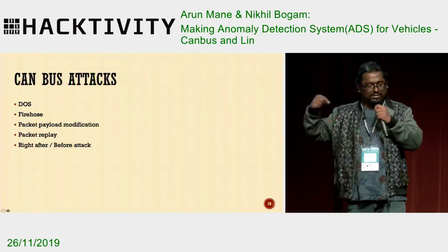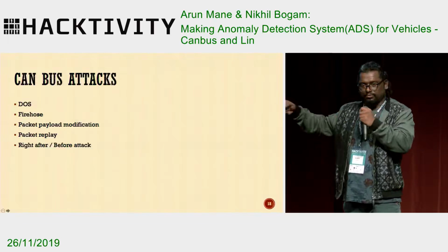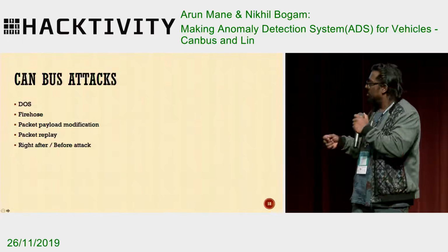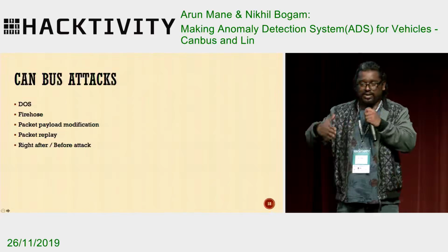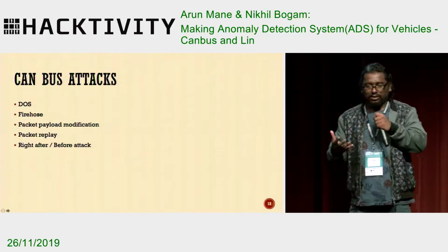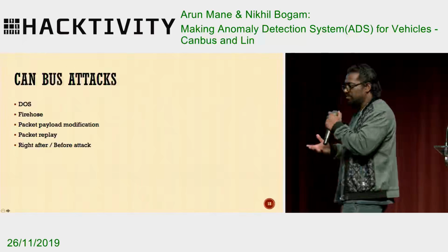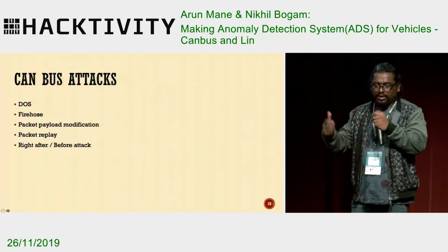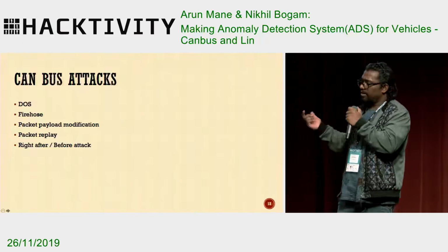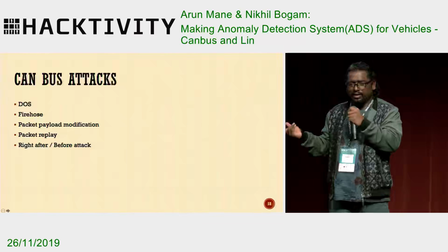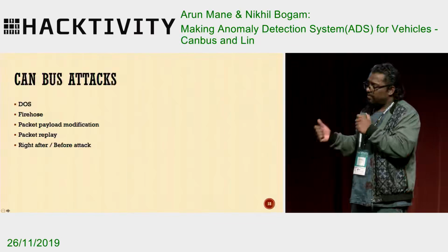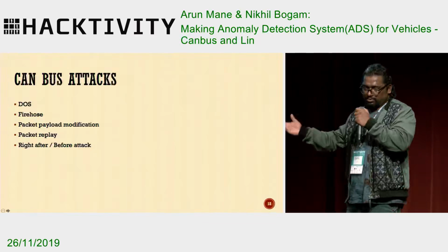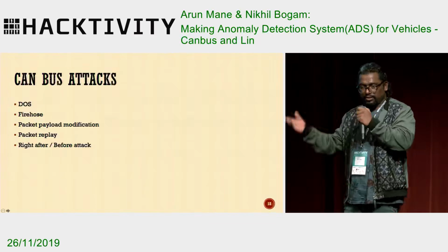If it is low, that means the message associated with that ID has a higher priority. The brakes and other sensitive functions or events have a very low arbitration ID. If the indicator shows 200 or 241, and the brake has an arbitration ID like 50, then 50 would be the high-priority message in the CAN bus.